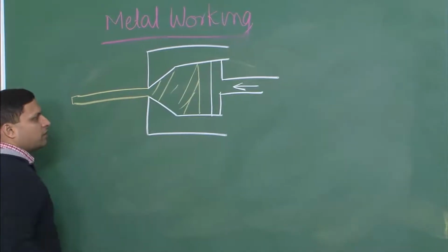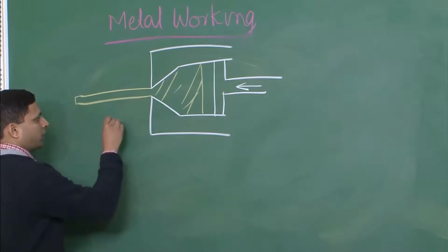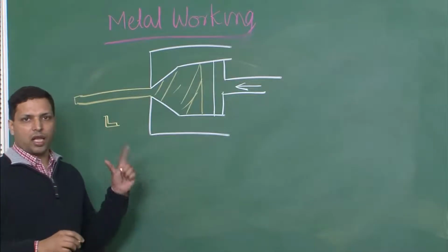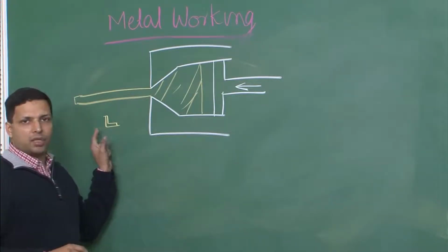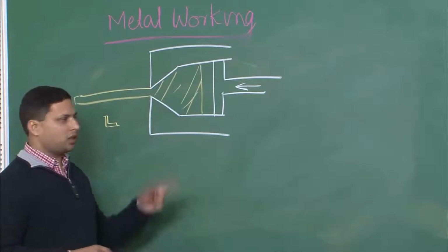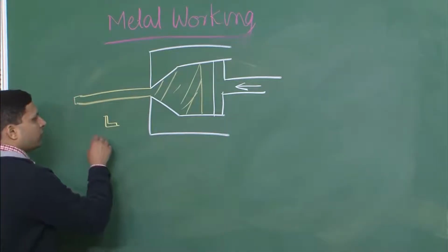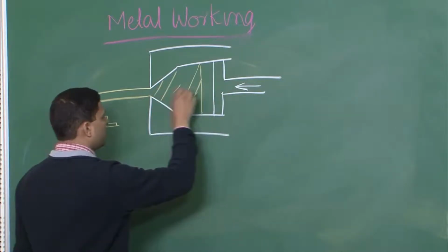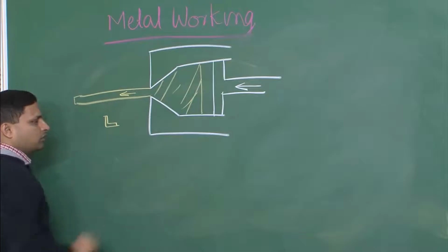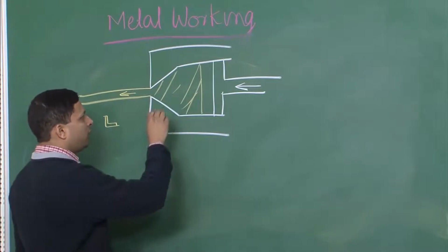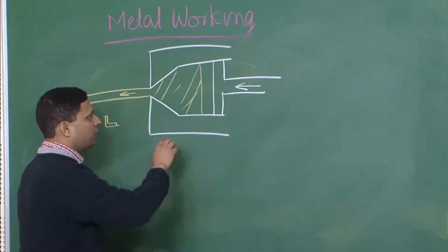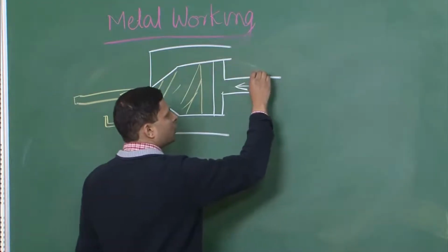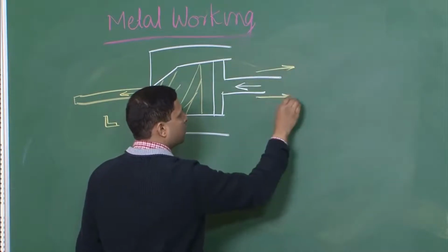Now, this longitudinal structure can be of any cross section. For example, it can be an L section. You remember having seen those L frames, the aluminum shaped L frames. This is how they are manufactured. They are extruded. Now, here this is direct extrusion, meaning the piston is moving in the same direction in which this part is getting extruded. However, we can have a different configuration, where when you press in this direction, actually the material will also come out in this opposite direction.